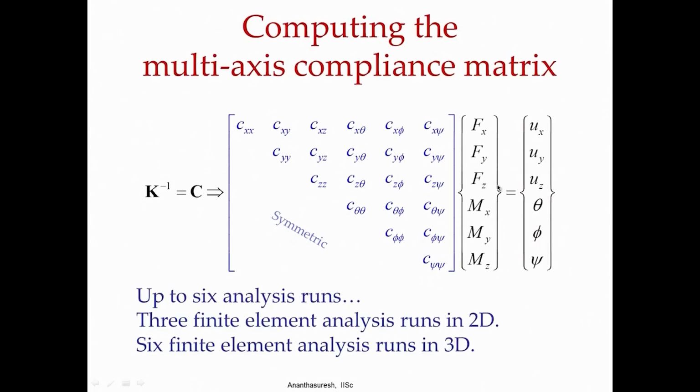If you look at the reverse of it, where I define the inverse of the stiffness matrix as compliance matrix C, then we can talk about this. Let us say if I want translation along the z axis, then Czz, because it is compliance, has to be very high, and all others have to be 0, because compliance is the opposite of stiffness.